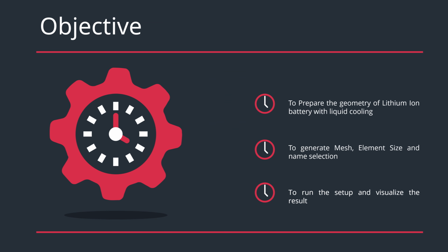So today's objective is to prepare the geometry of lithium-ion battery with liquid cooling, to generate the mesh element size and give the name selection so as to apply the boundary conditions in the setup part and visualize the result.